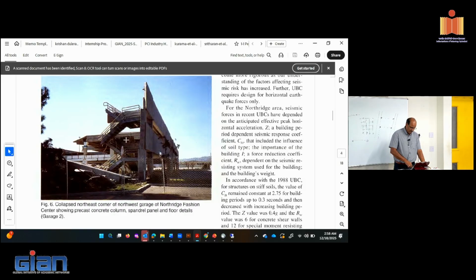One of the popular items is the staircase. Precasters make staircases and attach them to structures pretty successfully. You can see that in this case, the staircase didn't come down. They stood pretty well. But most of the failures are related to the beam-to-column connections.